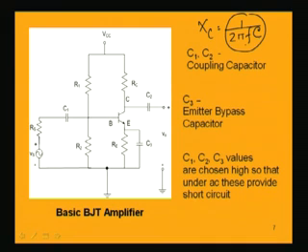And now, this overall circuit has both DC voltage as well as AC voltage, and applying the linear condition of superposition, we can consider the whole circuit in DC and AC separately. DC analysis we have already done in the biasing schemes discussed earlier. Now, under AC operation, the first and foremost thing is to draw the equivalent circuit for AC, that is, the AC equivalent circuit.